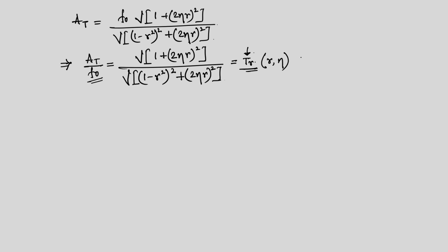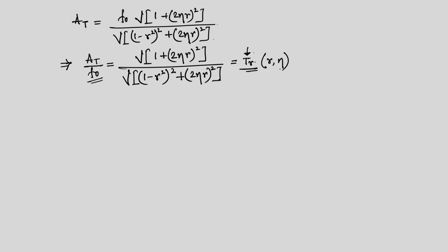So, the machine can operate at higher frequency. Obviously, as you increase, we have already plotted, you have to be careful about the nature of that expression for Tr. Nevertheless, at r equal to 0 and equal to square root of 2, no matter what is the value of damping, we will always have a transmissibility which is equal to 1.